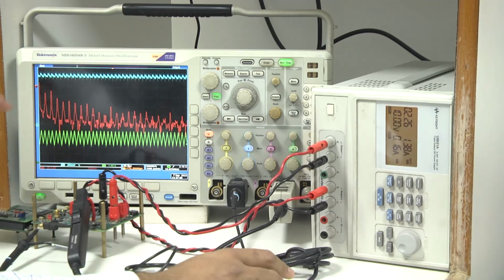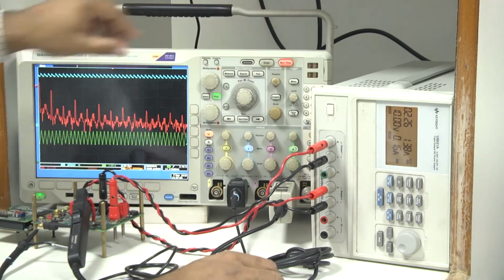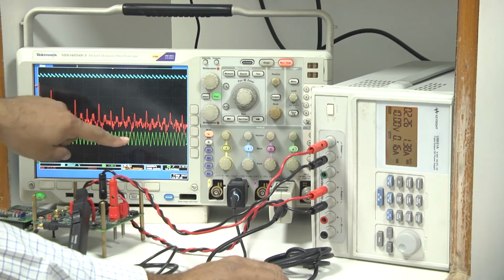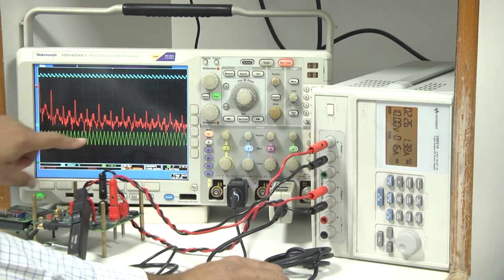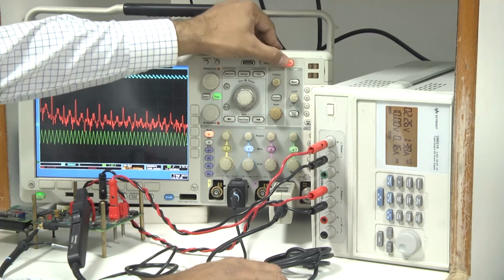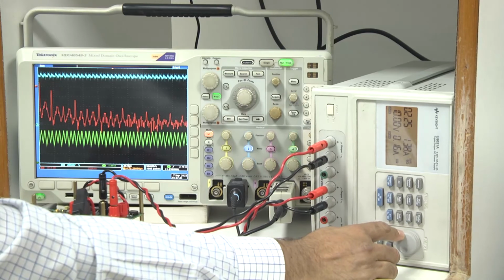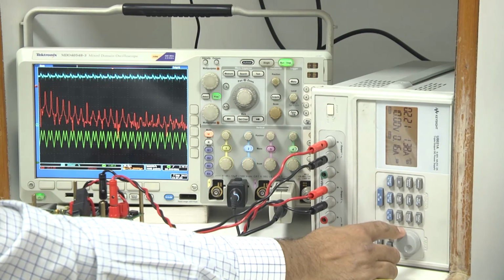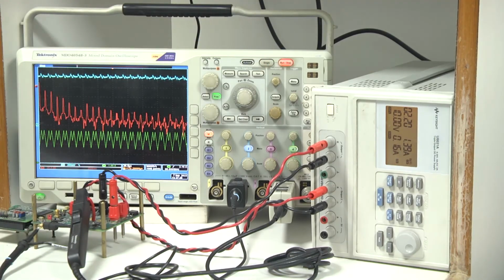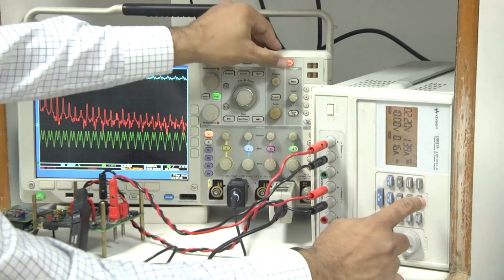That means, if we just stop it, you can see that instability is just about to start. Sub-harmonics are just starting to be created. They are not exactly matching; some cycles match, and in between there is a slow instability. Now we are coming to 2.2 volt. When we go to 2.2 volt, you can clearly see that there is sub-harmonic instability, and a spectral peak is coming, a sub-harmonic at 100 kilohertz, which we have shown in today's class.